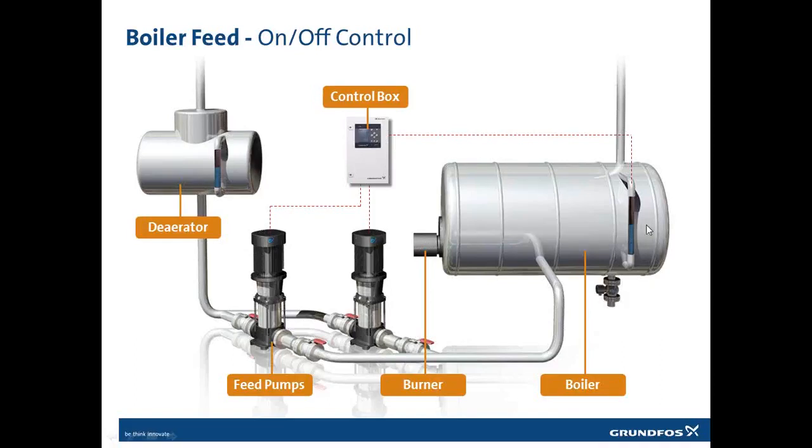It's a cheap system and works fine, but it gives us some challenges with cavitation in the pumps when they start, and we expose the boiler to mechanical stress due to the very large variation in water that is pumped into the boiler.